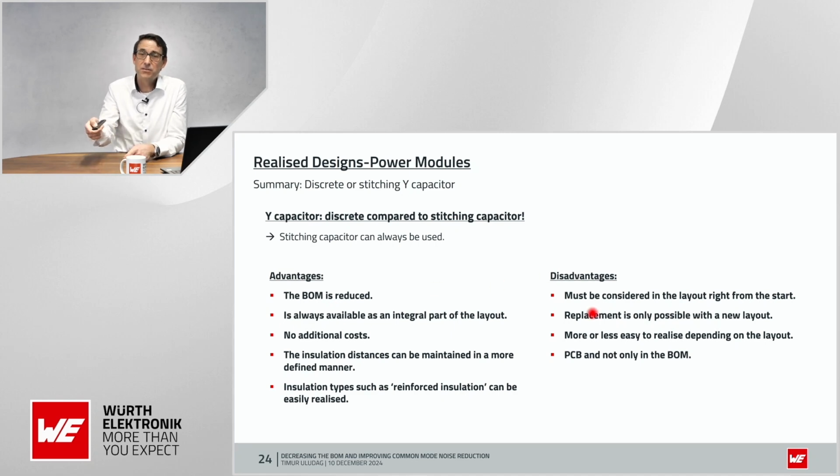As a disadvantage, if I want to optimize more, then it is not possible with an integrated version, because this automatically leads to a new layout. If the Y capacitor is placed discrete, you can take it out, take the next one from us and make your tests.